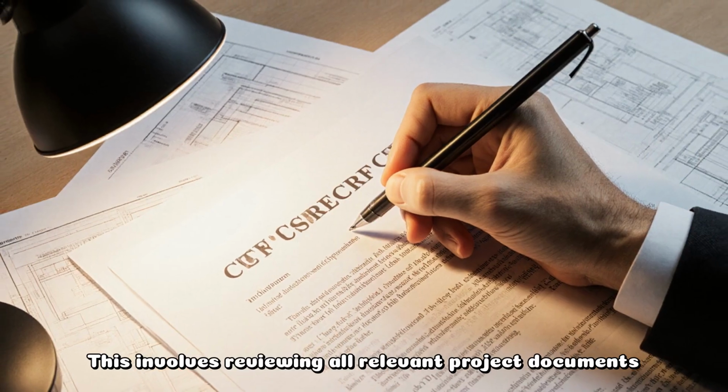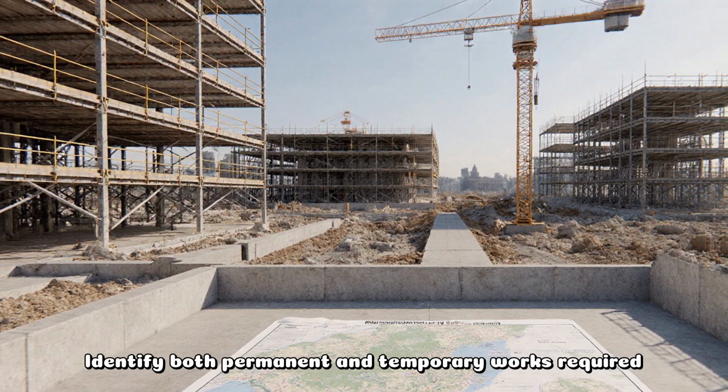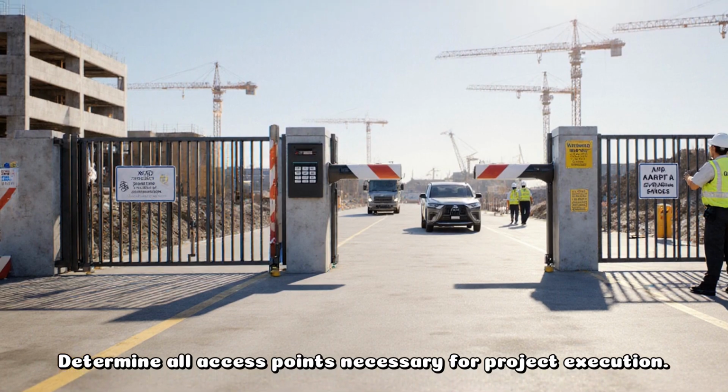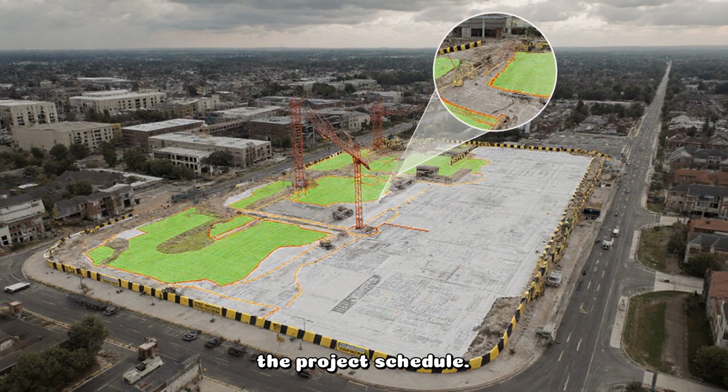Understanding the project scope is crucial before using scheduling software. This involves reviewing all relevant project documents thoroughly, identifying both permanent and temporary works required for the project, determining all access points necessary for project execution, and recognizing any potential constraints that could impact the project schedule.